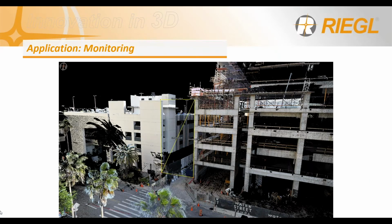Monitoring examples. This monitoring example here shows a building that's currently under construction going up next to a building that's already been completed. What the company is doing here as a monitoring project is measuring the distance between the buildings to ensure that the building that's currently going up remains perfectly plumb. Using the known factor of the completed building, knowing that it's perfectly plumb and level, helps to establish a baseline for the company to work off of and ensures that their building that is under construction is staying within their specifications.